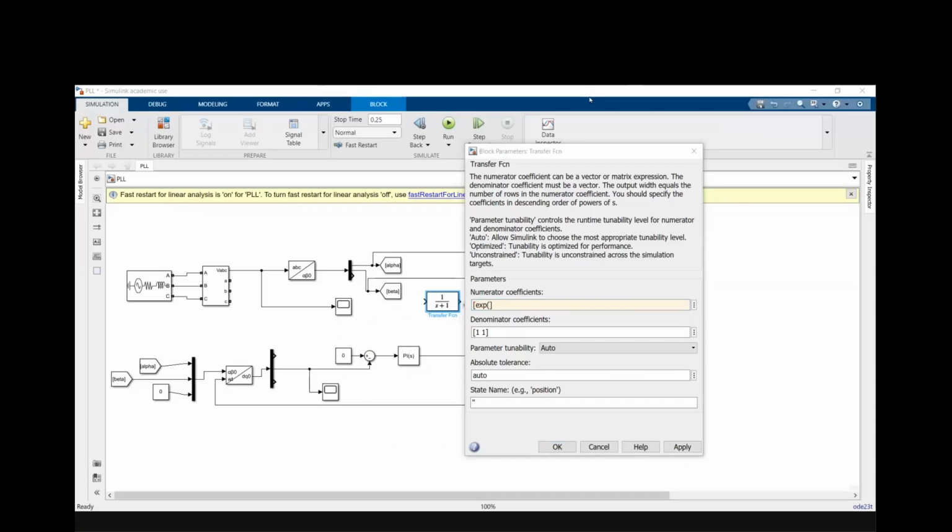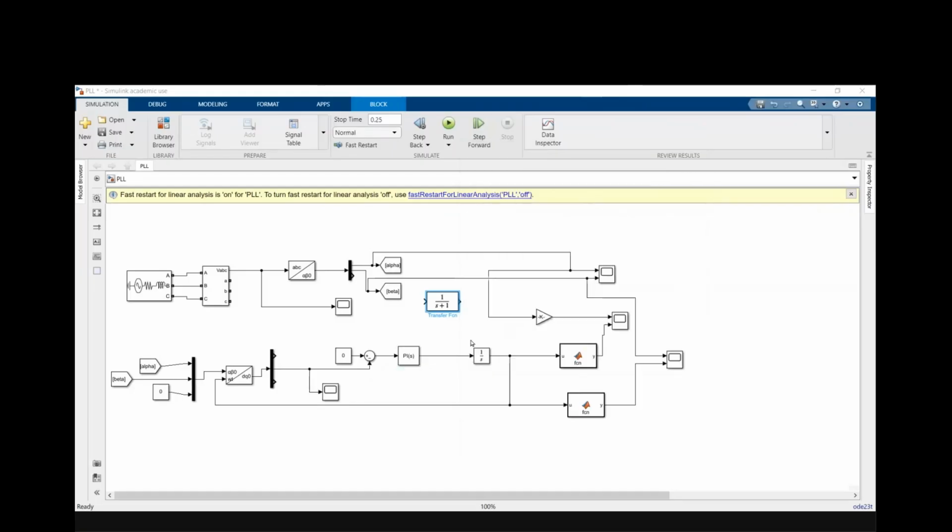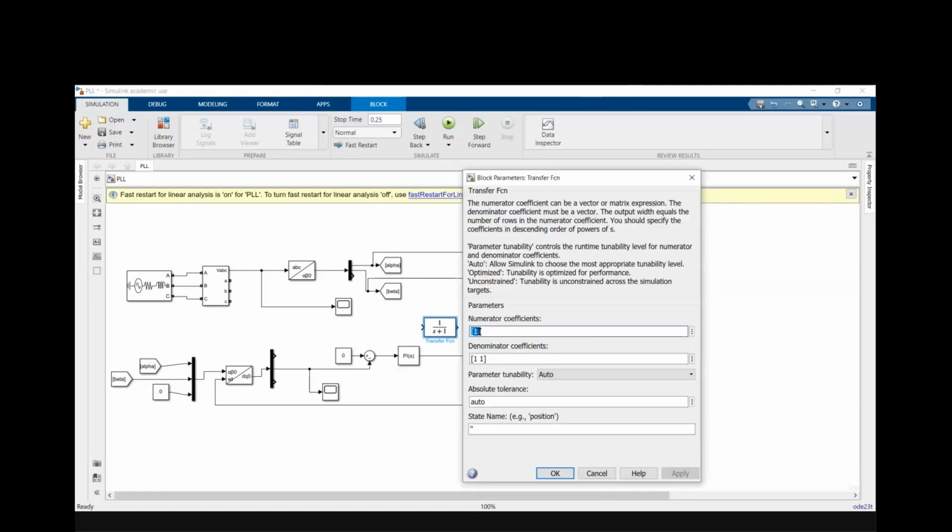So here we're using the PI controller as a low pass filter, right, sir? Yes. In this network, it is actually working like that. But in fact, I'm going to use that transfer function actually. That low pass filter I have to use, not just this 1 by S only. This is like a low pass filter. But for this, there should be some delay because you are using bridge converters now. So there has to be some exponential function of e power minus Ts.